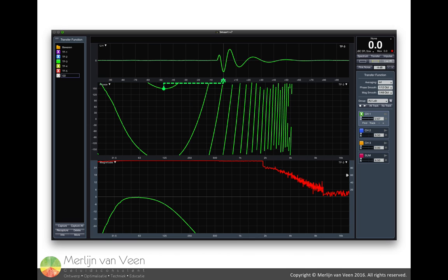If we move further to the right, we see that the frequency response, the phase response around 125 Hz is now the flat portion, and all the frequencies to the right of 125 Hz are leading, and all the frequencies to the left of 125 Hz are lagging.